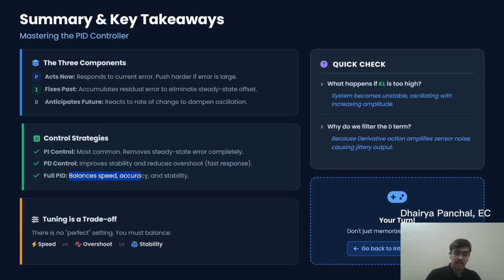And if you use PID, using PID is a little difficult, because you have 3 parameters that you have to adjust, that are KP, KI and KD, right? Proportional gain, integral gain and derivative gain. You have all these three values to account for. So in that case tuning will be hard for you, but when the tuning is done correctly, your system would be much stable, much better, and it would respond much better to your inputs. So those are the takeaways.